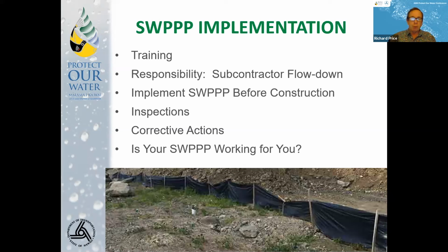Implement your SWPPP before construction. Make sure you have your controls in place before you clear and grub. Get the perimeter controls out there. Your process for inspections, and then corrective actions when you do your inspections.